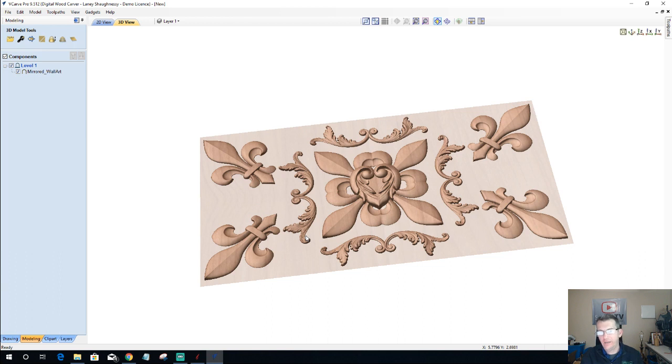It's an Aspire file if they save it as clip art. They can export it out as an STL. And then in your Vectric software, you just have to import it in as an STL or OBJ, as a 3D model file. But yes, you can have a model made by someone with Aspire. You can do that, like we've done here.